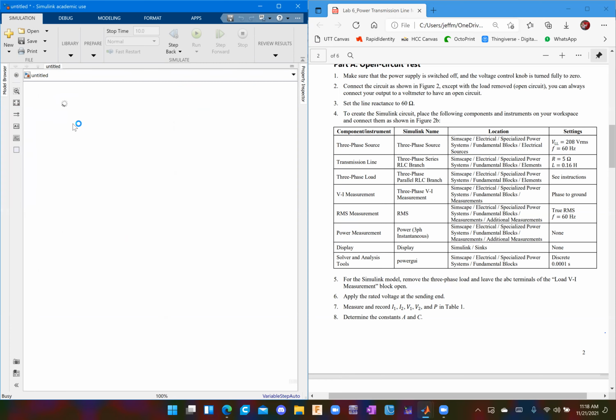You just click it and it pops up. Now, if you notice, when it's not selected, the label disappears. If you want that label to stay there, which will make things a lot easier later on, click it once to highlight it, hover over the three dots, don't click it, just hover over it, and then go to Show Block Name, and that will leave the label on there.